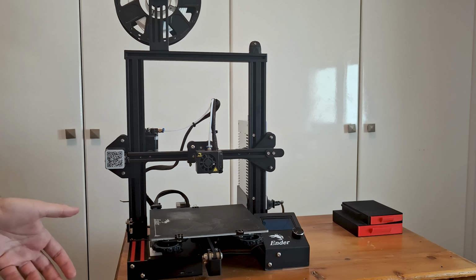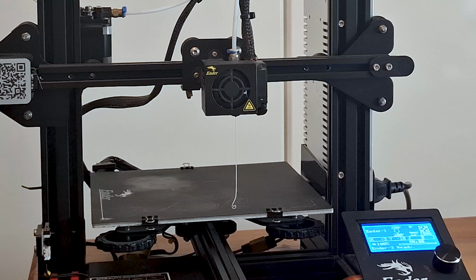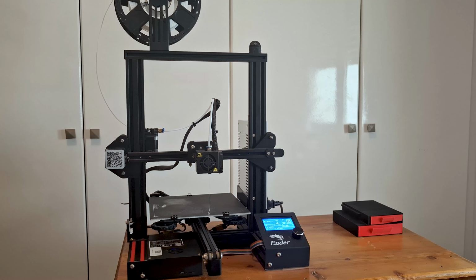I will now show you the procedure to start the printer. So basically I just power it on the right and then I will be feeding the filament inside. But before that I need to heat up the extruder. Now that it's up to temperature, I will push the filament from the side, starting by the extruder. As you can see, filament started to pour down from the nozzle. This allows us to change the filament or change the color and many other things this way. We need to do it while the printer is heated.